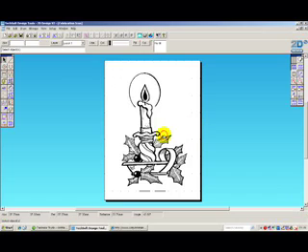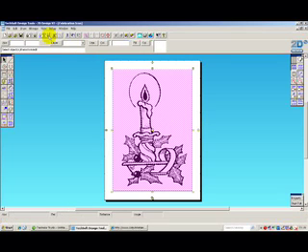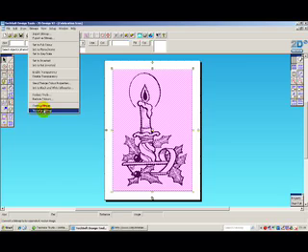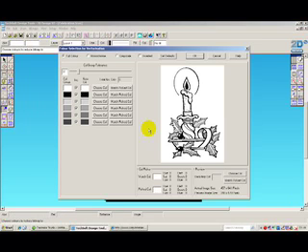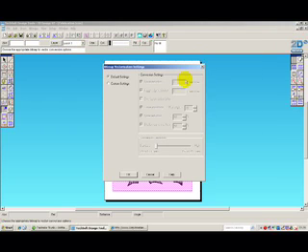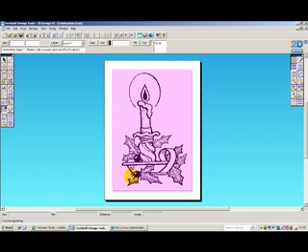That's no use to us for laser cutting. We need to turn that into a vector drawing, a line drawing. So you go to bitmaps and vectorize, just changing the quality here, getting rid of all but the black in the drawing, so it's a simple line drawing, clicking OK. Click OK, and now that's converting into a line drawing.